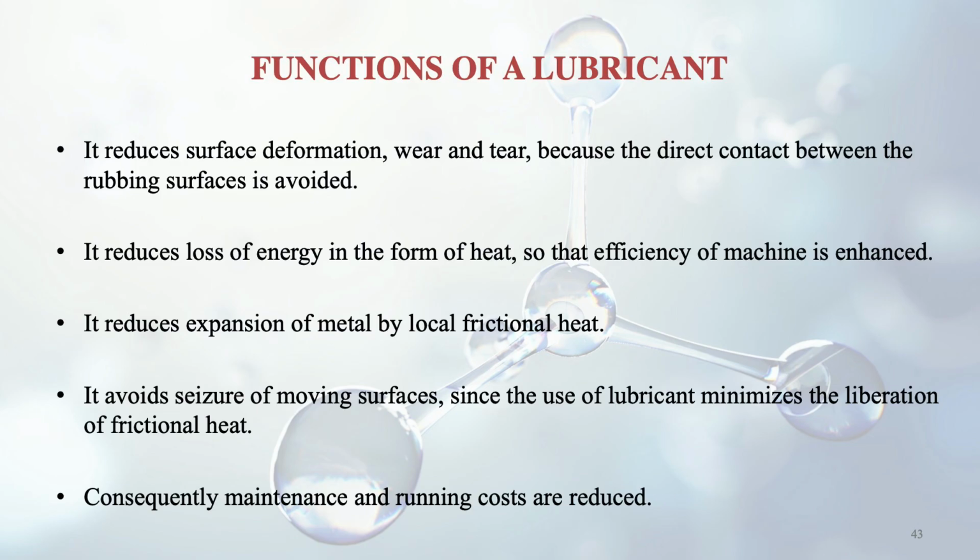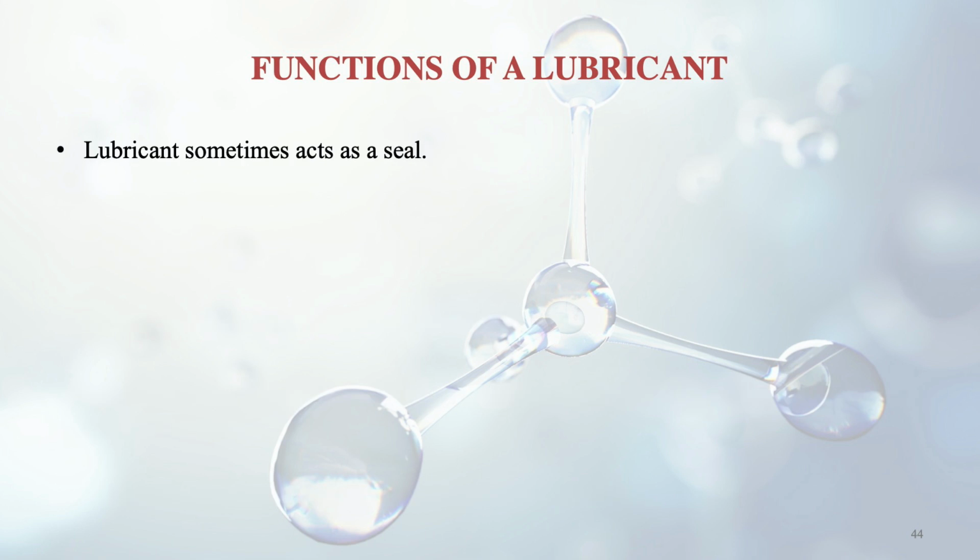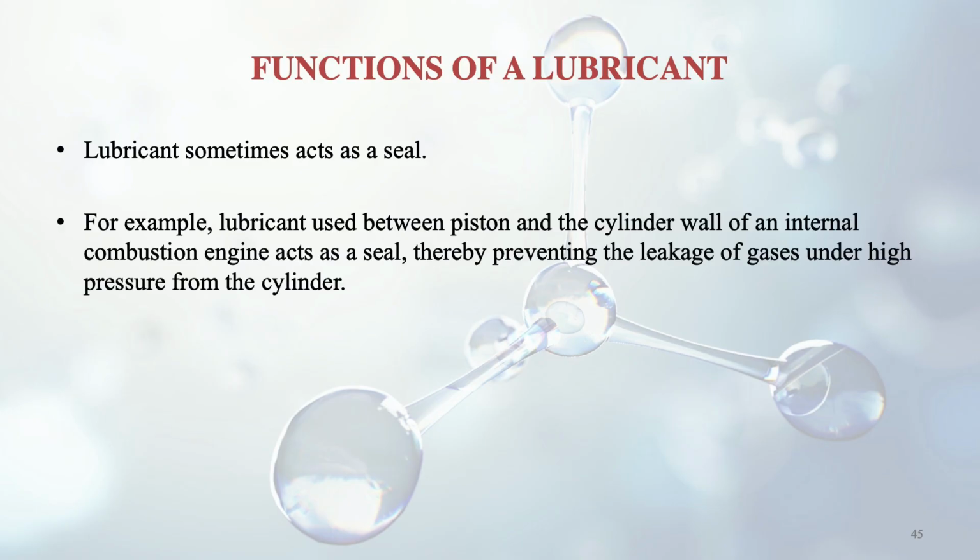And maintenance and running costs, obviously if energy loss is less, then the costs are reduced for maintenance and running. And lubricant also acts sometimes as a seal, meaning it will seal a gap or something like that, so that there is no leakage. For example, lubricant used between the piston and the cylinder wall of an internal combustion engine acts as a seal, thereby preventing the leakage of gases. Actually the gases are produced inside that cylinder, they will not leak out under high pressure from the cylinder, and hence we will get proper expansion stroke and power stroke.